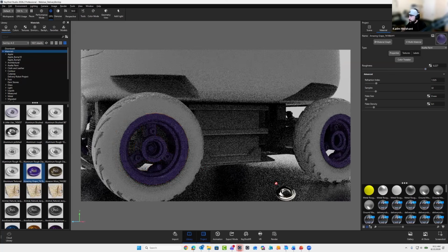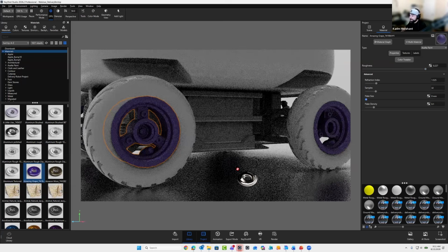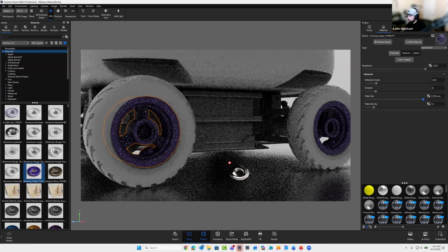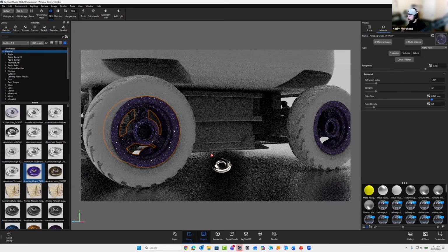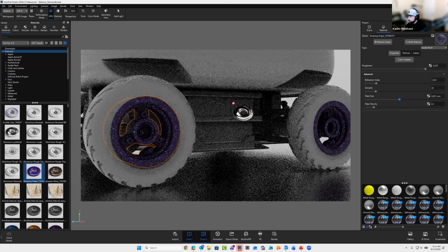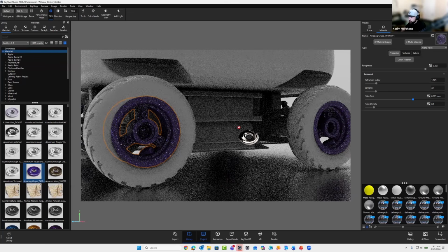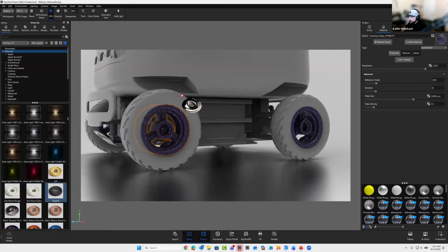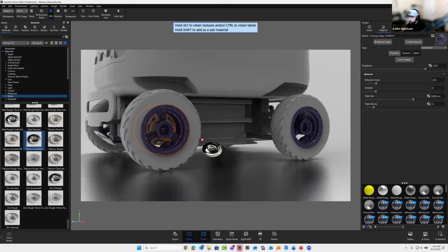Sometimes you are importing your CAD data. Ideally, again, coming from CAD, your CAD data is really, really strong. All your bodies that you're going to want to split off or add materials to or animate in the future have all been CAD modeled separately as individual bodies. But sometimes, like the case of this model, a few parts that I might want to apply materials to are not separated. So if I click on this screen over here, I'd like to isolate that screen, but you'll notice that the entire body's selected.